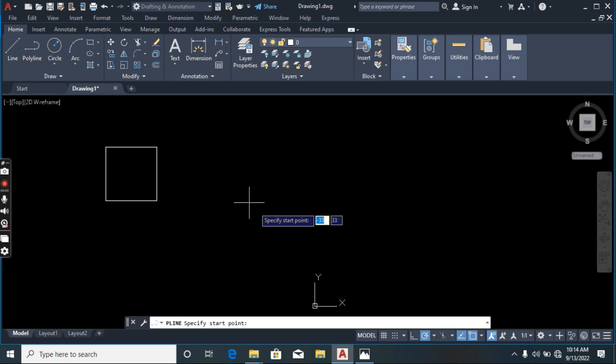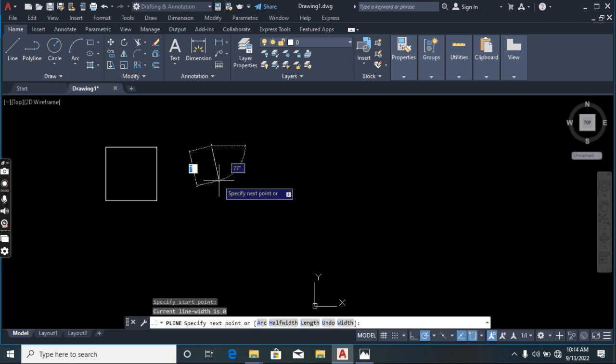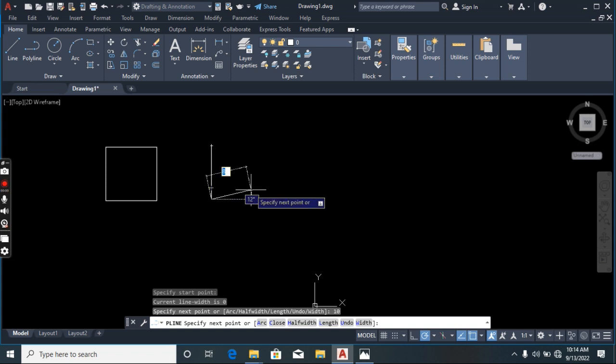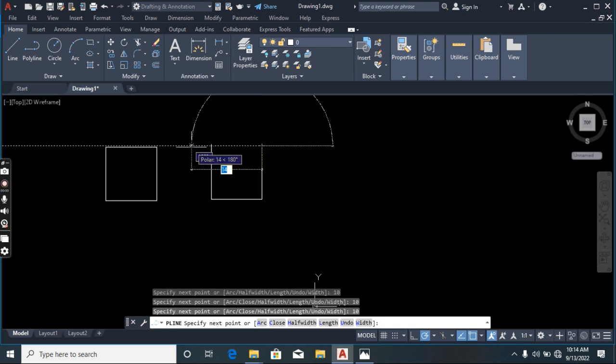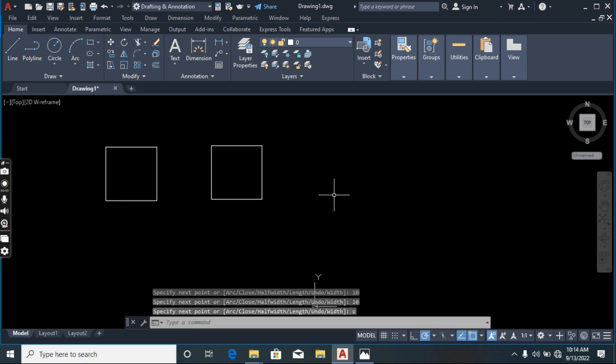You pick a polyline, you want to do a square tool, enter. See, the same thing, 10, and you make sure it's straight and type 10, enter, take it up, type 10, enter, take it this way. You see, with polyline, when you want to complete your square, you can just type C and just complete it, or you can type 10, or you can just touch.